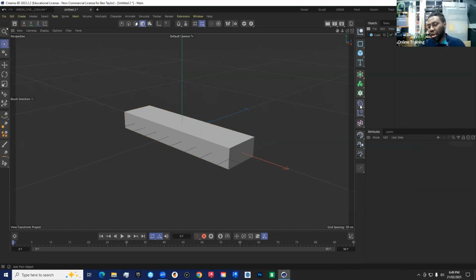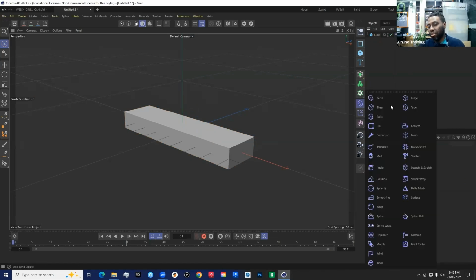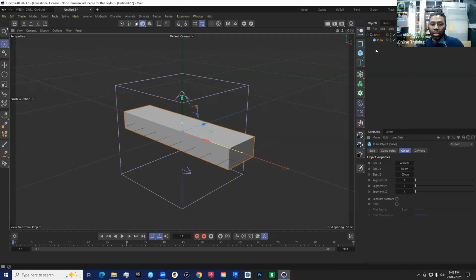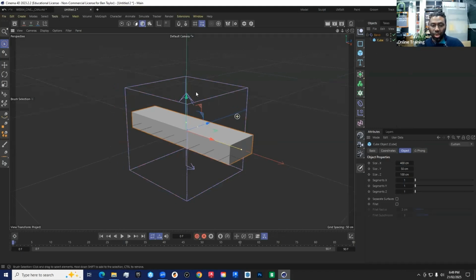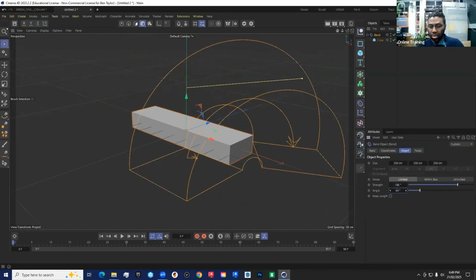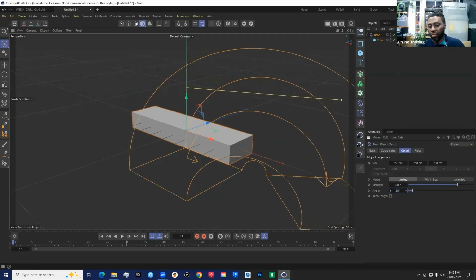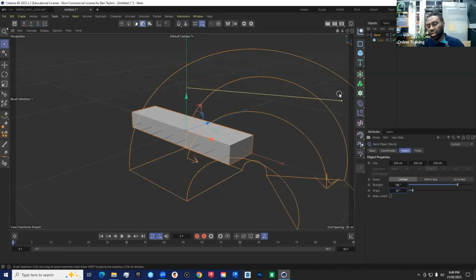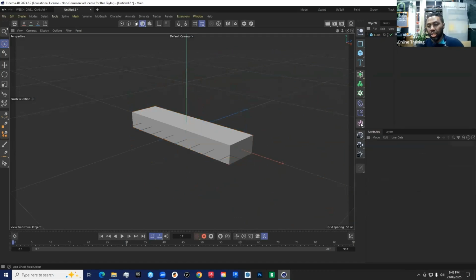And we also have a series of purple modifiers, which are more like distortions. So we can bend, shear, bulge, and distort objects. So if I very quickly put my deformer in there, we should be able to see those purple lines. And let's make the deformation. So you can see the parameters of the deformer, and then I can get my block to do that. So essentially, one is a series of modifications, the other is a series of deformers. We'll play around with those as we go.